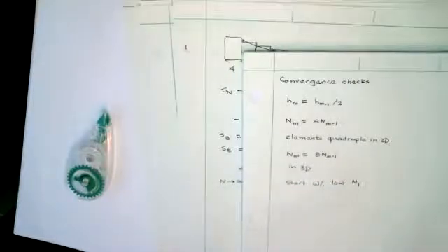Your first mesh better not have too many elements, or you're going to run out of room. Computational facilities are getting so good nowadays that even if you start with a few thousand, you multiply by 8 a few times, you can live with a few million elements.